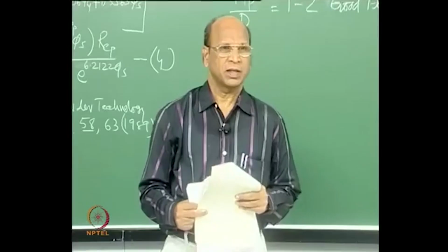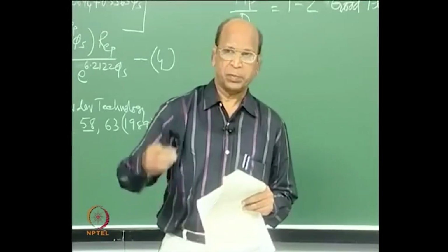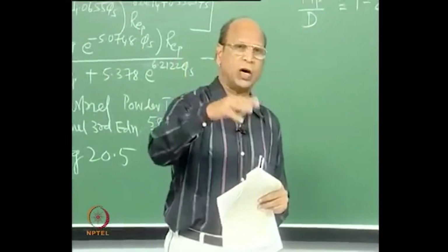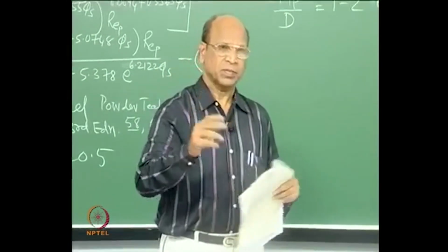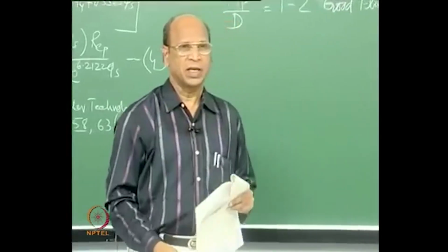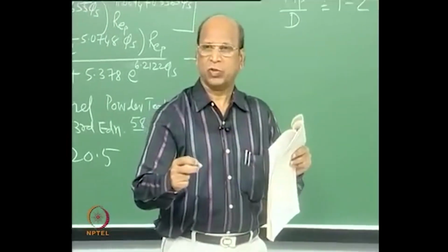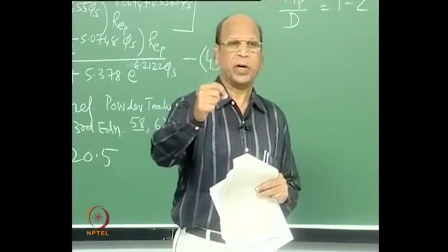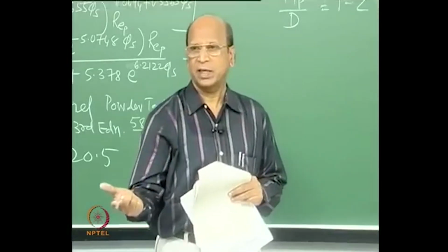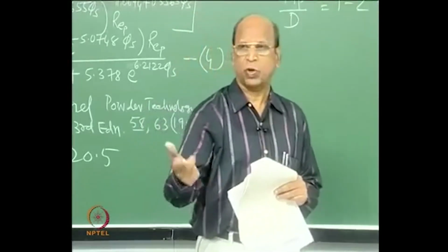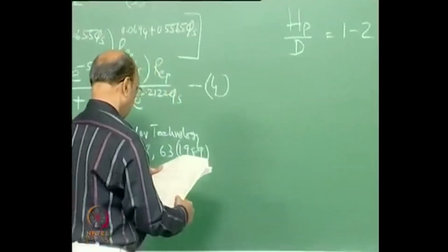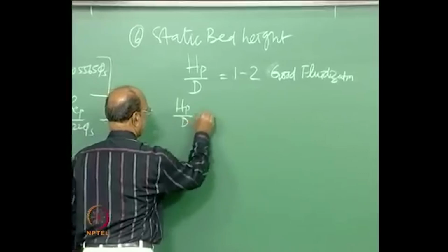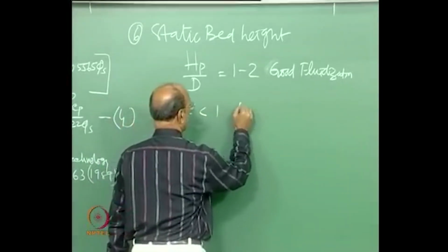Good mixing in solids. Yeah, that means good contact between, not mixing. Mixing also you can have without good contact, because when you have bubbles and all that. So, uniform fluidization and also good contact between solids and gas. That means each and every particle must have very good contact with the fluid, either gas or liquid. That is what we mean by good fluidization. But when you have Hp by d less than 1, you have what is called shallow beds.